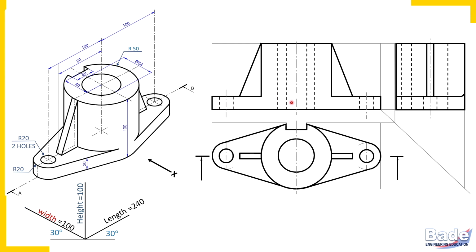Cylinder and the base plate, there was a boundary here, but I have removed that, and I instructed you that when two portions get cut by a cutting plane, the boundary between the two portions of the object does not appear in the sectional view. Then why must we not erase this boundary or this boundary? Try to understand.